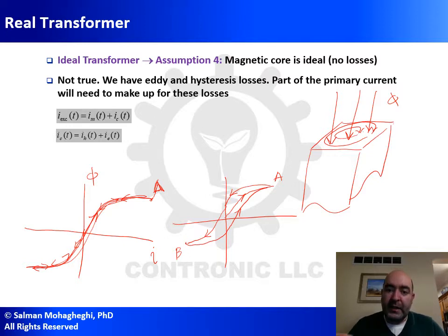And we say that there's going to be magnetic losses associated with the area under this magnetization curve, the hysteresis loop. So now when you connect a magnetic core, you wrap a winding around it and connect it to a voltage supply, the current that flows through the circuit has two roles. One role is to magnetize this core by generating a magnetic field intensity H, a magnetic flux density B, and a magnetic flux.